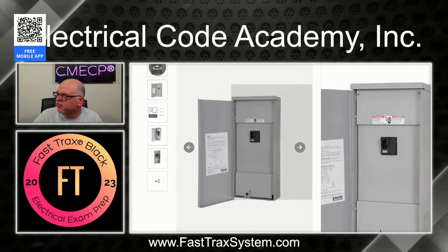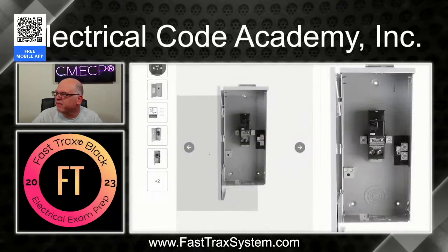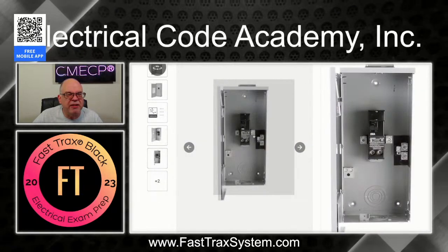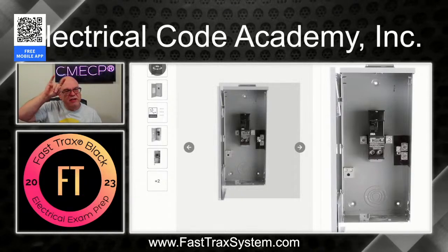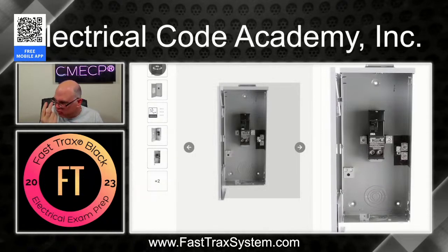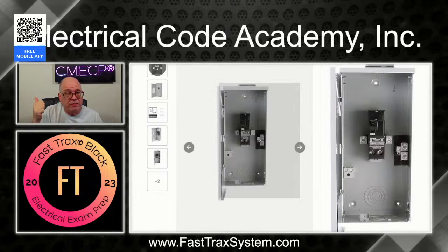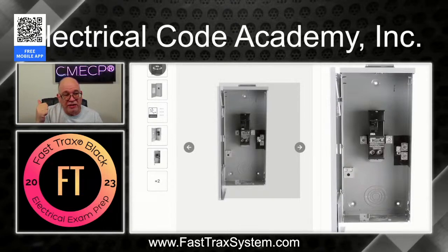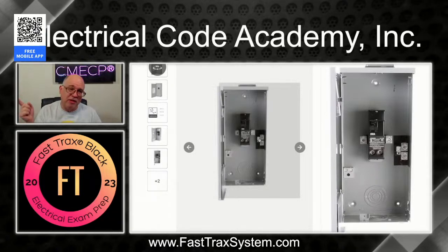It's just a 200 amp. That's it. And when you look inside of it, I'll give you a little sneak peek here. As you can see right here, you've got the service conductors come into the lugs, and then the load side at the bottom is where your feeders are going to come out and going to supply a panel, either just inside, or maybe even somewhere else in the structure, right? But this is the only thing outside.